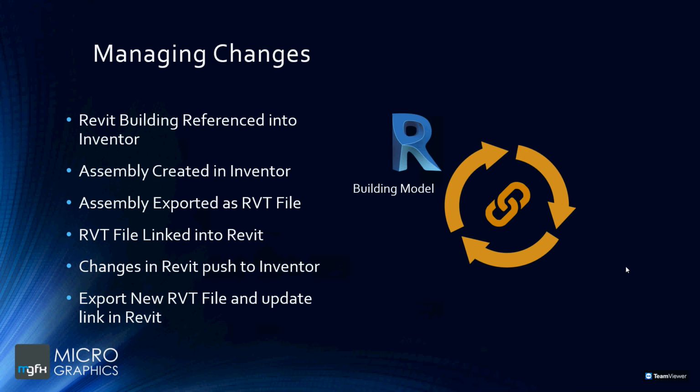We had the first step where a model was supplied by the architect, and that was imported using AnyCAD into Revit. So there we have the building model to the left of our link. That model is prepped by the architect and brought into Inventor. The assembly was designed in Inventor around this Revit model. So that's that coordinated design that I mentioned earlier, potentially using the Revit model as reference to guide and move the Inventor designs as well.